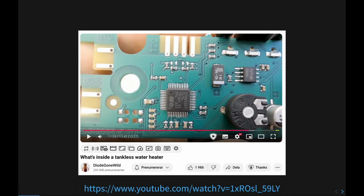But which consumer devices, you might wonder? Well, here's your typical and cheap tankless water heater running on an STM8, as this teardown video from Diode Gone Wild, famous YouTuber, shows. Most common functions that our low-power microcontroller does are controlling power regime of IGBT transistors, driving peripherals such as LCD screens, and reading values from sensors such as NTC temperature probes and other boards connected to I2C buses, just to name a few. The microcontroller is also capable of outputting PWM signals, for instance, which can drive motors.